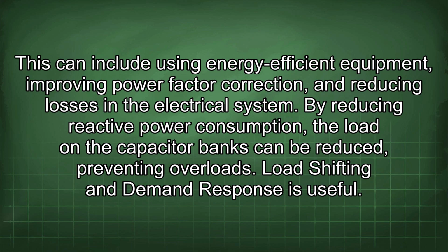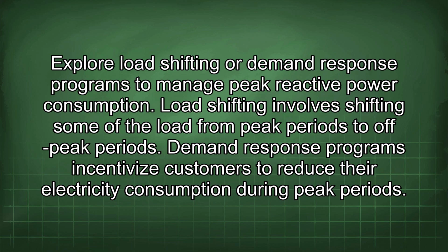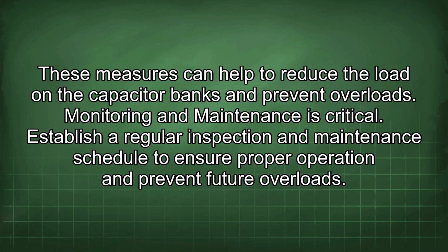Load shifting and demand response is useful. Explore load shifting or demand response programs to manage peak reactive power consumption. Load shifting involves shifting some of the load from peak periods to off-peak periods. Demand response programs incentivize customers to reduce their electricity consumption during peak periods. These measures can help to reduce the load in the capacitor banks and prevent overloads.